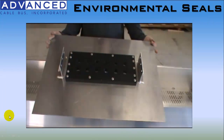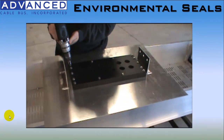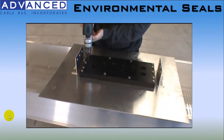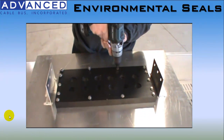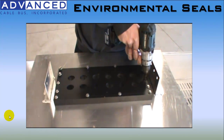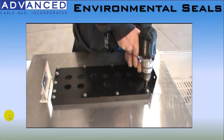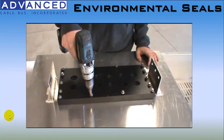For installing the environmental seal, whether on a wall or for a piece of equipment, the first step is to remove the bolts and remove the seal block in order to clear the opening. This would allow you to first ensure that the opening in your wall or in your equipment matches your requirement.